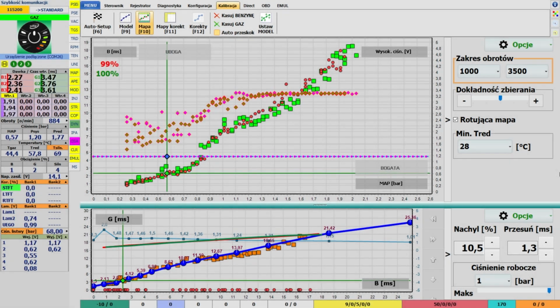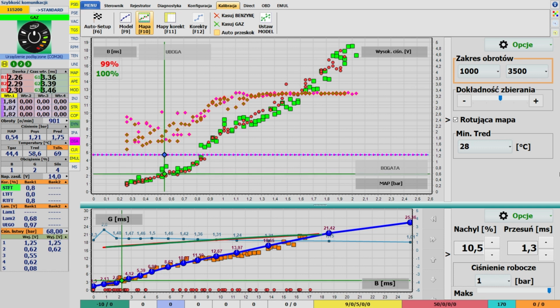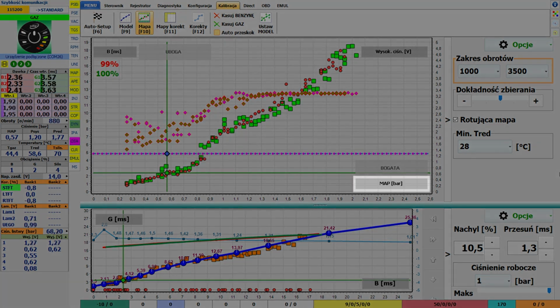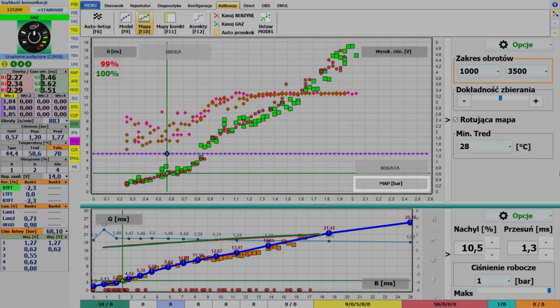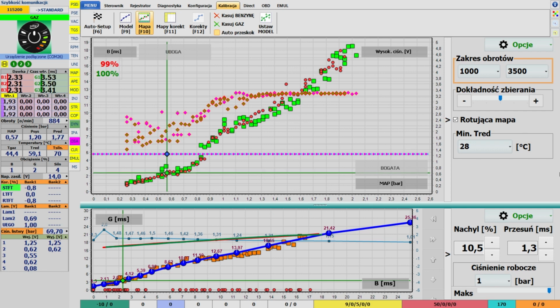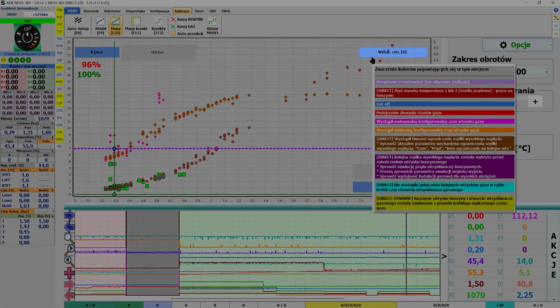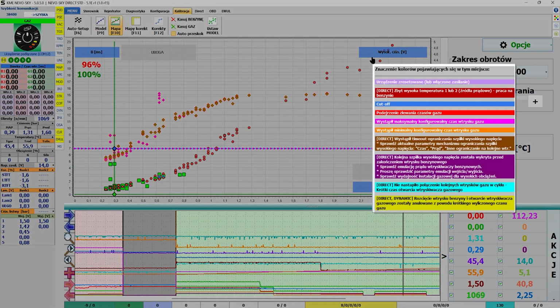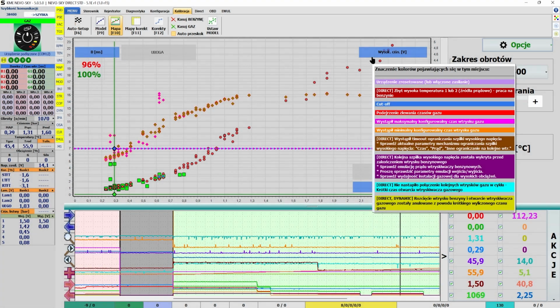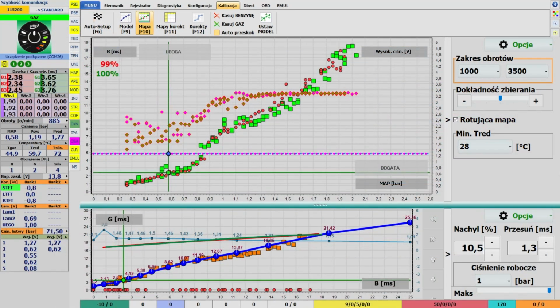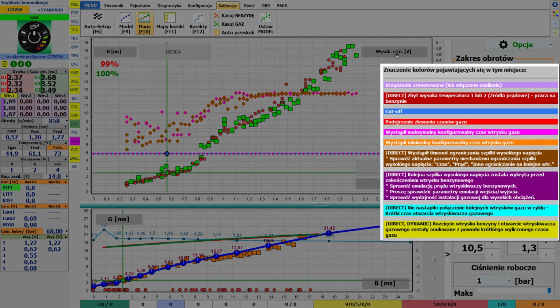Each axis has a designation that tells you what each value refers to, and in square brackets, the unit is shown. Remember, during a test drive, the axis markings may change their color depending on the current conditions or an event that has occurred, e.g., cutoff, injector merging, or minimum and maximum gas injection times. To find out what a particular color symbolizes, right-click on any of the markings.